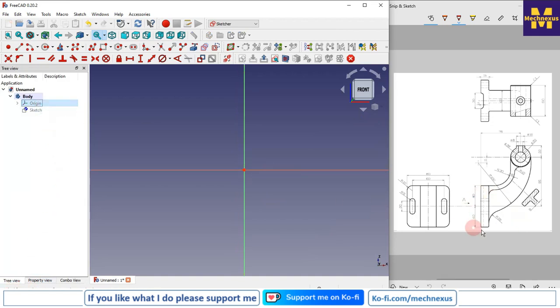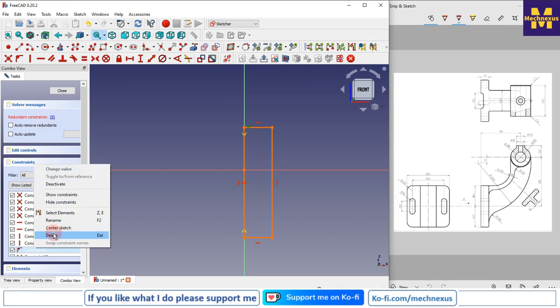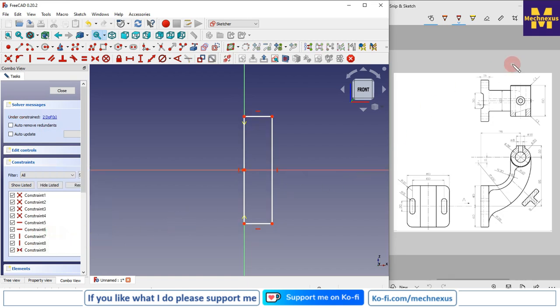Here the dimension is 40 plus 40, so I will simply select a rectangle and make it symmetric. I will select this and this and this. Here is a conflict, so I will select it and delete it. Its thickness is 15 mm, so I will give 15 mm here.